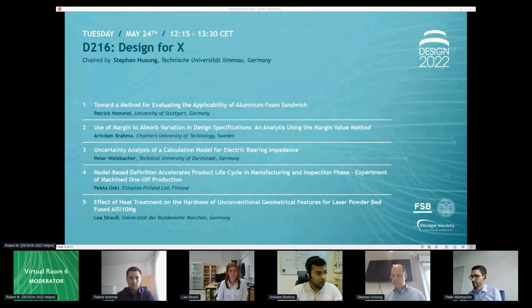Yeah. But we found out that actually it's not really possible to use model-based definition in CAM processing. And we found out that, for example, Siemens NX, there are only a few customers in the whole of Scandinavia who are able to use it, and because they use very special products, they will employ that. But let's say in the inspection phase, you can use automatic creation of the CMM code, and that actually gives you huge time saving on the process.